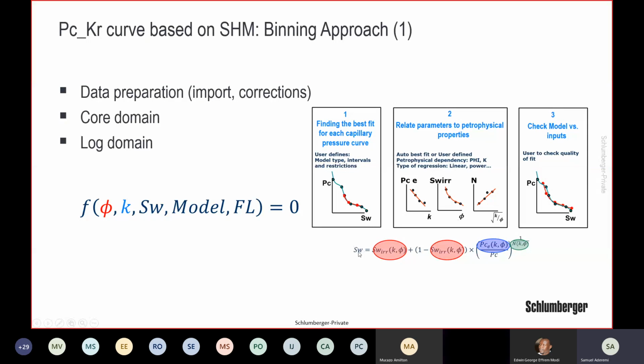water saturation, you can see if I'm using the Brooks-Corey correlation, there are many correlations like I showed you last week, but this one is particularly Brooks-Corey, and it says that the water saturation equals the SWirr, the irreducible water saturation. But actually this value here is the irreducible water saturation that corresponds to the model.